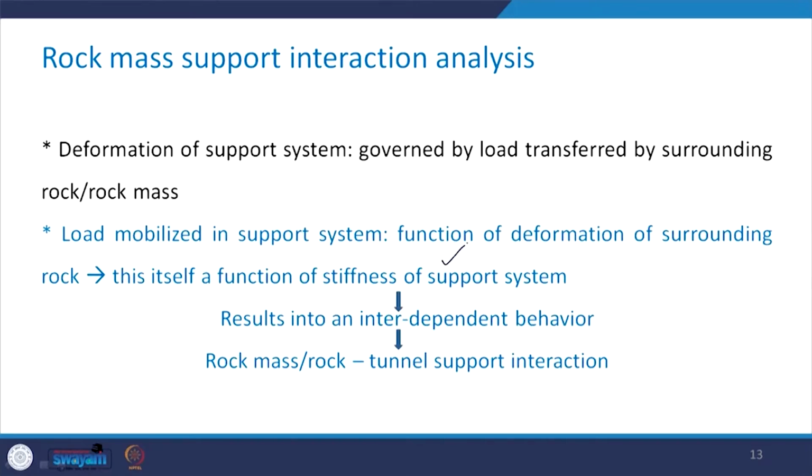One aspect is the deformation of the support system, which is governed by the load transferred by the surrounding rock or rock mass. The second aspect is the load which is mobilized in the support system. This is a function of deformation of the surrounding rock, and this deformation of the surrounding rock itself is a function of the stiffness of the support system.